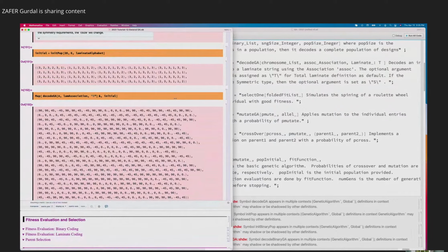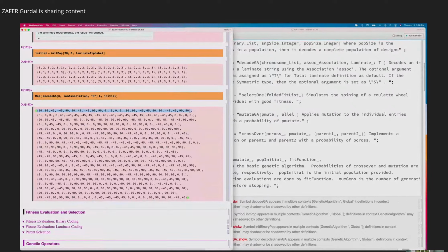Each has different properties, different A matrices, different B matrices, different Tsai-Wu criteria, different stiffnesses, different vibration frequencies. Nevertheless, each design is part of a population, and when I use something as an objective function, it will understand. We will have to compute the appropriate quantity for each laminate. Okay? Now that's the fitness evaluation part. I think we actually came to the fitness evaluation part in the binary coding case.